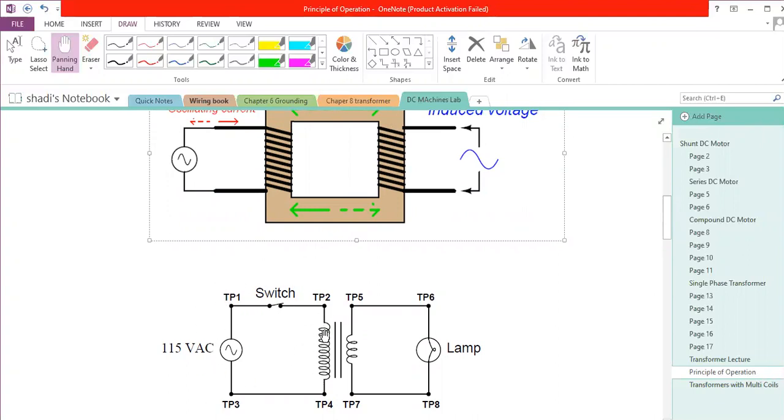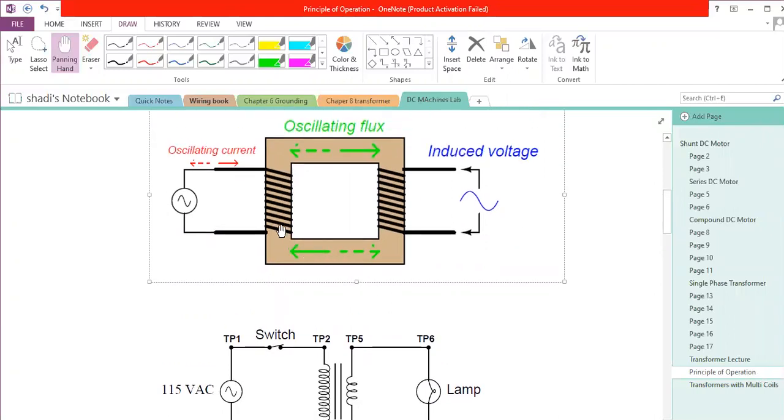And then here we have a winding. And then these two parallel lines represent the core because we are transferring the magnetic field. And then we have the secondary. Now, again, the power supply must be AC. We cannot connect a DC power supply to a transformer and expect that the transformer is going to generate voltage, because, again, I forgot to emphasize this important point: we must have an oscillating magnetic flux that is changing with time, because this is the main principle in order to generate voltage at the secondary.